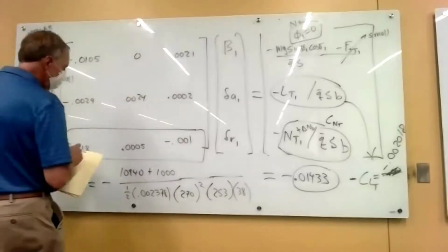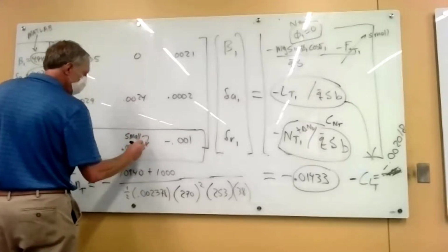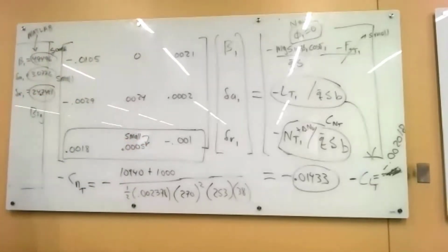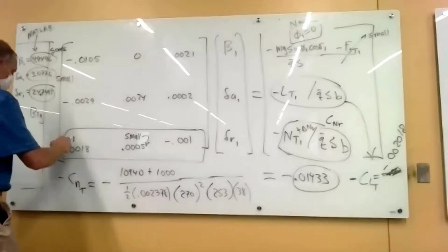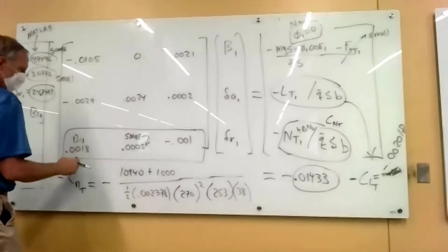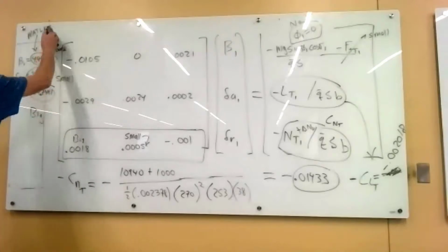And if we notice that this number here is small, that's the aileron effect, the yaw from the ailerons. We get some, but we can make an approximation and say, okay, this is the biggest number here. That's smallest, so maybe we can shortcut this 3x3 problem and just calculate the rudder that we need based on that equation only.